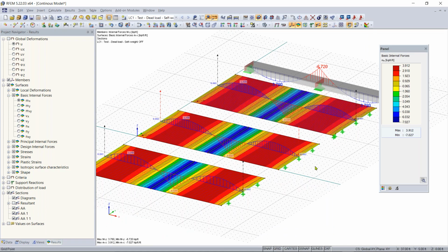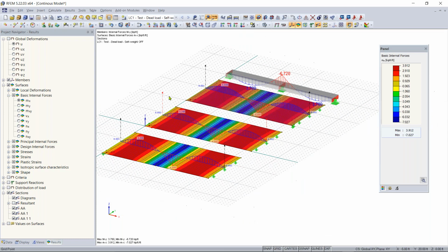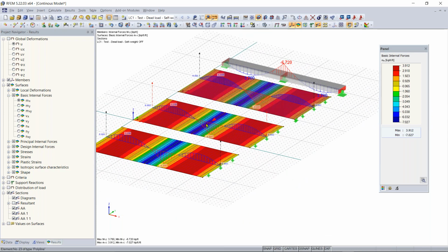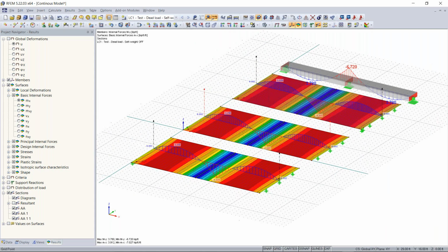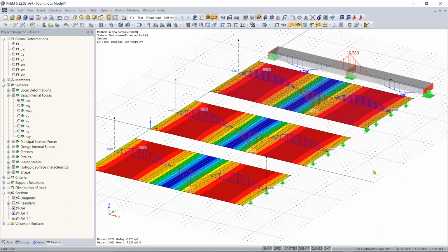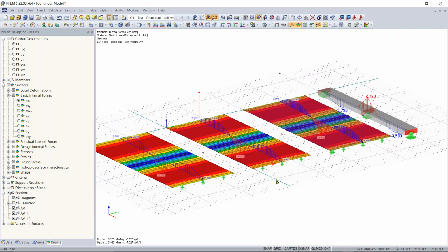When we're getting into a surface element whose thickness is relatively comparable to its width, then you would want to convert this to a solid element, a 3D solid element. We have some recommendations in our FAQ of when you need to consider a solid element instead of a surface element in order to get accurate results. A good way to think of this is a brick element. If you're trying to model something that looks more like a brick, then probably a solid element would be better than a surface. So hopefully that answers your question.